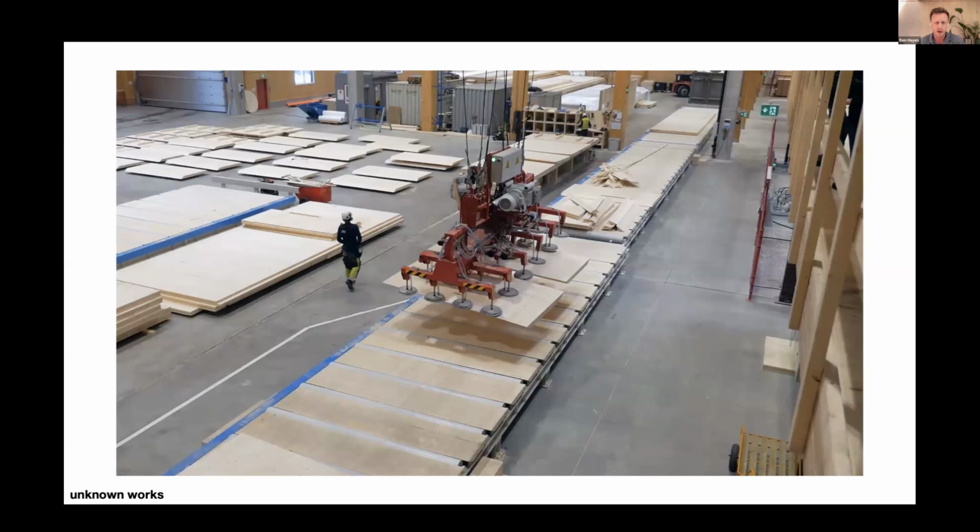An interesting starting point within this framework was coming together with Xilonor CLT and ConstruktCLT, whom Jim and Sen on the call represent. We started with a cubic volume of CLT, which is 25 cubic meters, and tried to explore innovating a hybrid species CLT, eucalyptus and pine layered together as an external structural system.